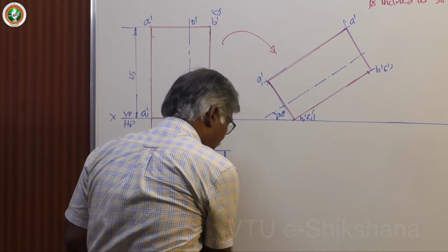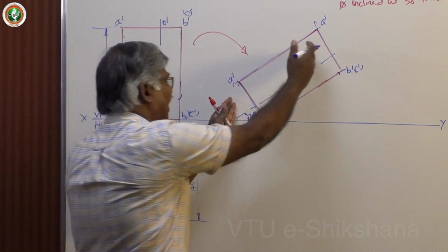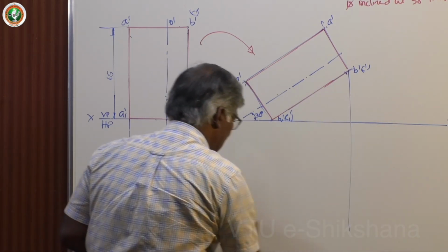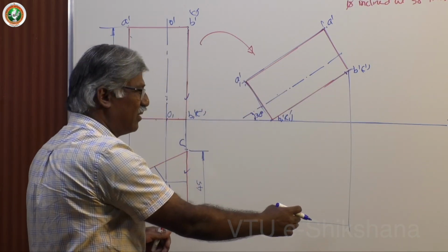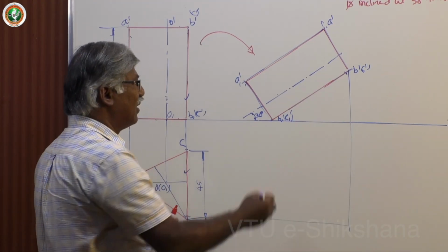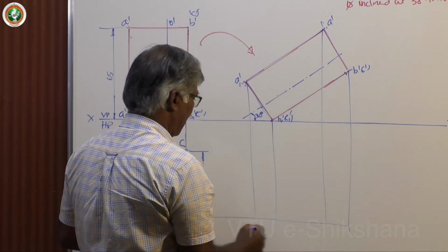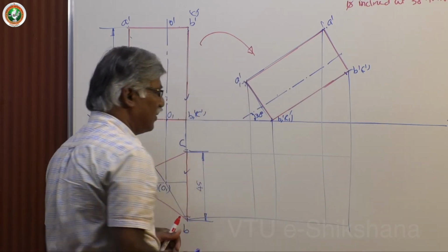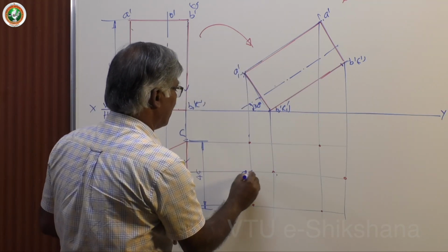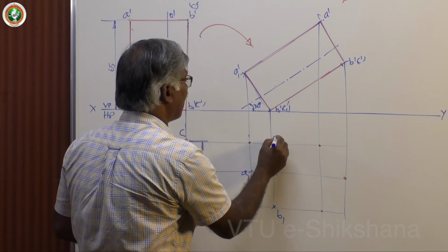Now let me project this top face and base. It is something like projecting two parallel laminae, that's all. Now I always prefer to have stoppers here, the extreme right projection and the lowermost projection, so that you should not go beyond this. Then draw this. Okay, next keep this and one more line. So this is A. This is A. You must have patience to do all this, otherwise it leads to a lot of problems.